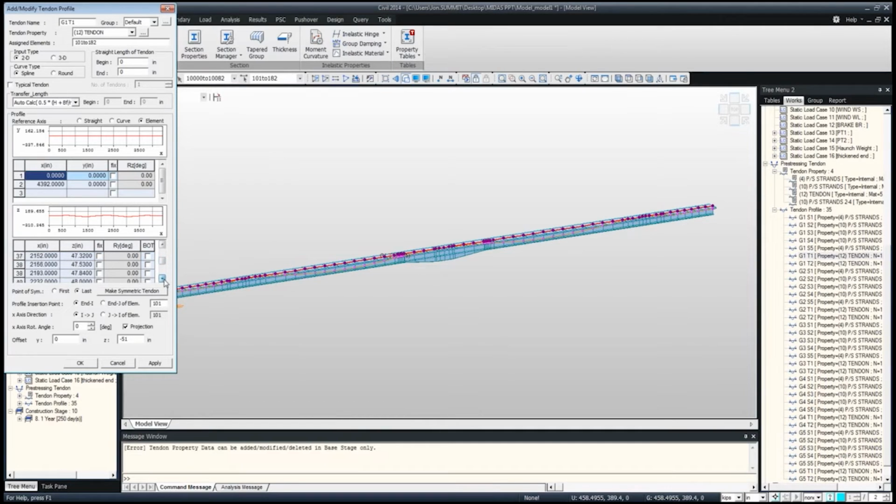And using the spline, I was able to put in the more discrete points and allow it to create the spline between that. Now, because when I established a section property, I built everything from the top of the bridge deck downward, I need to put a Z offset downward from the bridge deck to the baseline of where I want the bottom of the lowest point of the tendon to be, and that's where this -51 comes from.